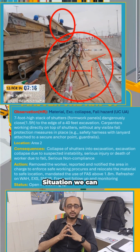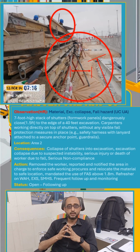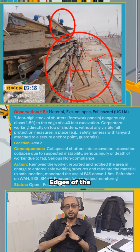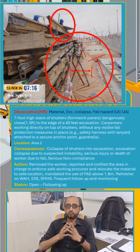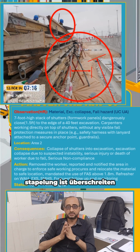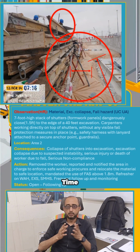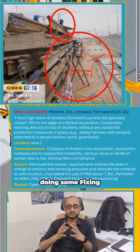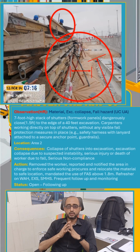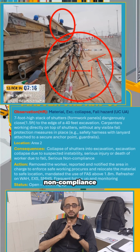Here in the situation, we can see that our construction team removed big heavy shutters, approximately 1 ton each, and then stacked them very close to the edges of the excavation, at some points only 1.5 feet away. The height of the stacking is also exceeding the height of the barrier, reaching 7 feet. At the same time, carpenters are doing fixing work on top of the shutters without any fall protection or fall arrest system. So this situation is posing a serious fall hazard, excavation collapse, material collapse, and also serious non-compliance.